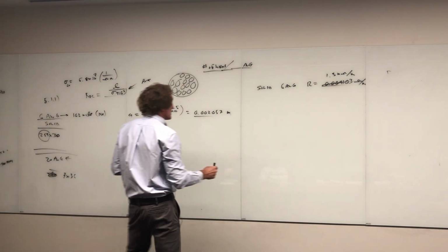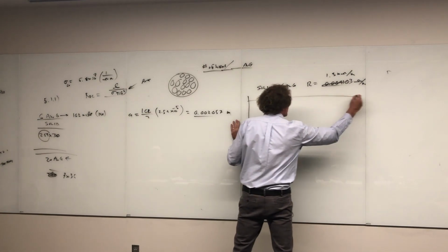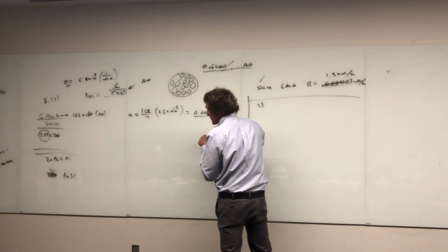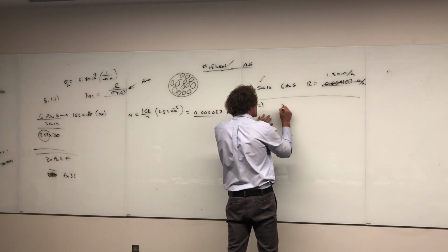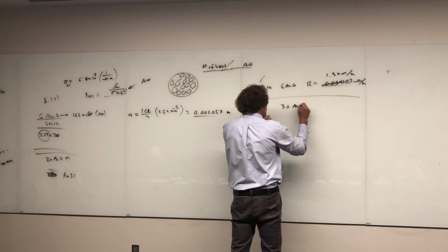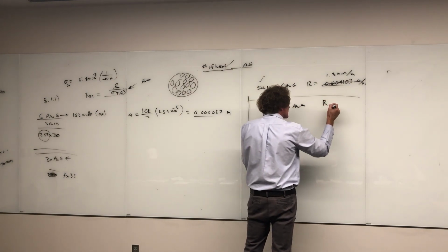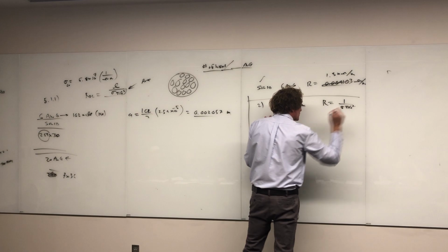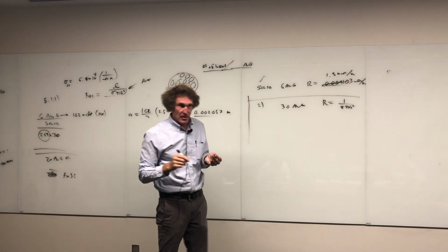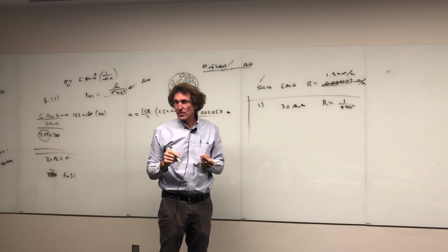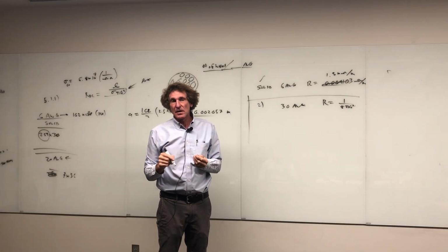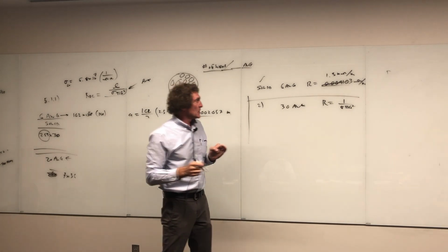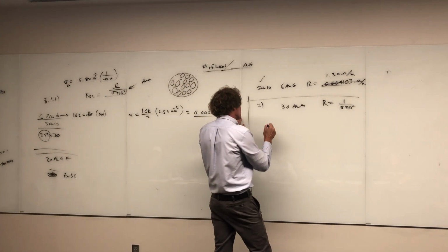All right, now for this one, for part 2, let me just do this, because this is solid. We checked first one. For part 2, now we've got 259 by 30. So first, for 30 AWG wire, we know the resistance is always going to be per unit length, 1 over sigma pi A squared. We're after the A for 30 AWG, right? If you look at that, what do you see for AWG 30 solid wire? What's the, in mils? Or give me the diameter first. Diameter is what?